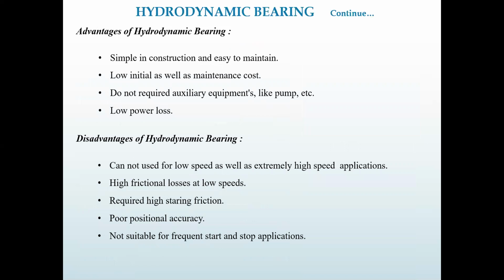If you do not want metal to metal contact, then enough speed is needed. Because of that, the oil pressure can be generated properly and the separation of the bearing and journal can occur.